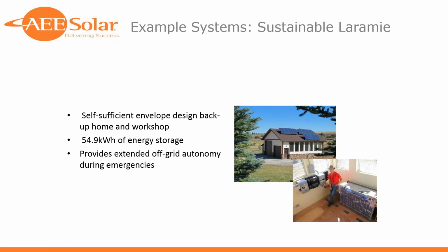And I've got here a couple of sample systems. This is an LTAC system in, I believe, Laramie, Wyoming. Array up on the roof. Lots of energy storage for extended outages. I believe this is an FP2 with 2 FlexMax 60 charge controllers. So a fairly simple off-grid system, it provides lots of autonomy for extended outages. And because he's got the array co-located with the power electronics equipment, it's a DC system. I don't believe this one is grid-tied, so again, fairly simple.